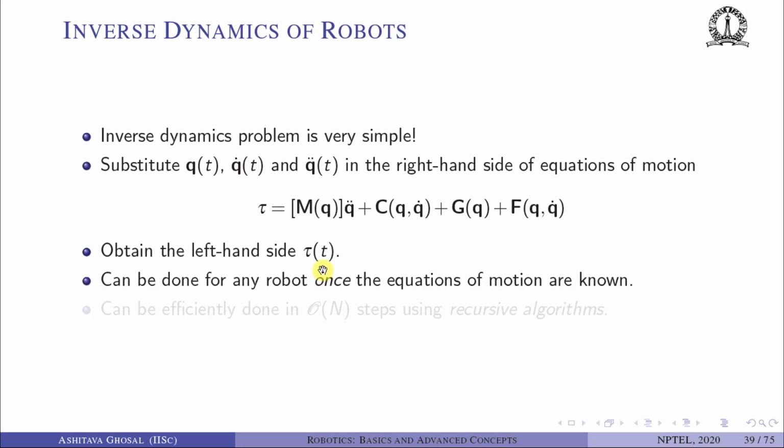So it can be done for any robot since the equations of motion are known. You can do it very efficiently because we will see later that this can be obtained in O(n) steps using what are called recursive algorithms.